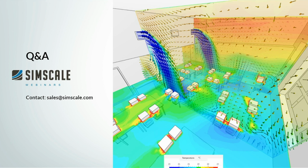and other structural parts. Also in the convective heat transfer analysis, you can, on the boundary condition level, put the specific thermal properties of the facade in as well, meaning the heat transfer coefficient, the thickness of the facade, and the external conditions in the outside environment as well. So with simple constant thickness facade elements, you should be able to model that accurately with just the convective heat transfer analysis. Thanks, Richard.